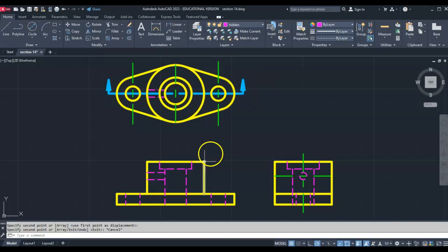So this arrow is showing me that in my front view, I'm going to remove this side of it, and I'm going to be looking in at the internals here. So to how my front view would change now, this line would get trimmed because it would stop right here, because that's where it's going to stop. Any of the hidden lines that are being cut through to be shown, so pretty much everything is being cut through at the same level here, those will all get changed to object.